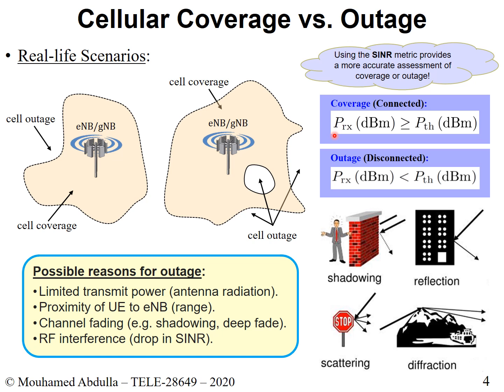Now, I have to admit that quantifying interference is not easy. So if you talk about real life, how on earth are you going to know all the interfering devices around you? You're not going to know that unless you're doing this in a controlled environment. And in general, this is not the case. We're talking about real life deployment. You deploy your cell. You don't know the other interfering sources, right? You might be able to look at it on your spectrum analyzer, different signals that you're able to detect, but in general, you don't know these sources.